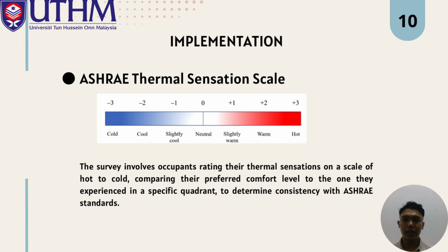So this is the ASHRAE standard thermal sensation scale. Zero stands for neutral, negative one stands for slightly cold, and positive one stands for slightly warm. So occupants can vote their rating according to this scale.